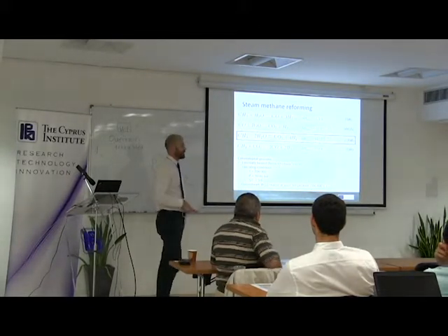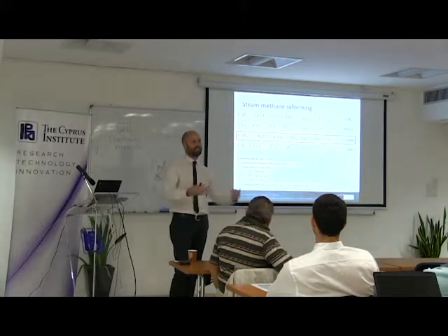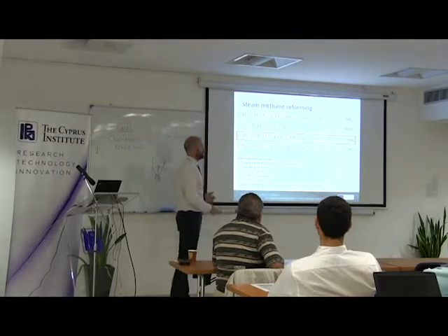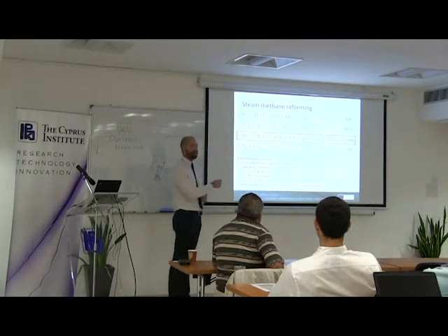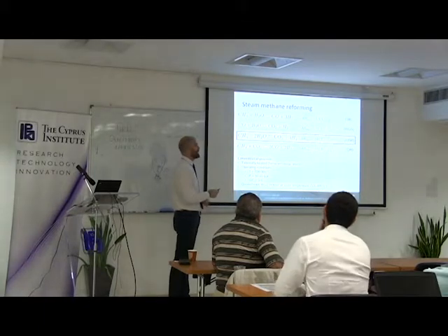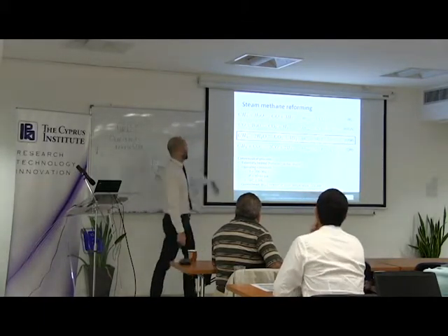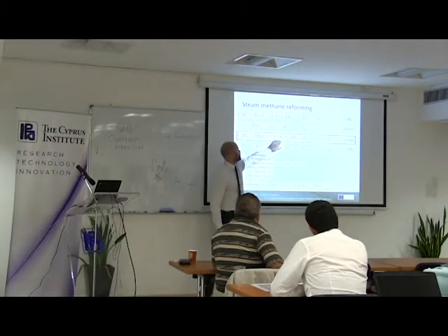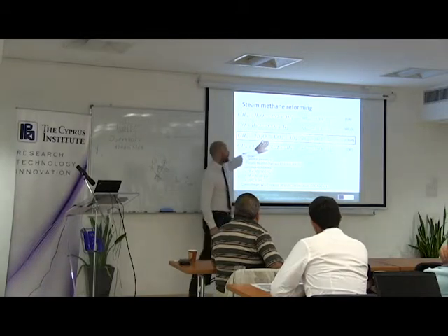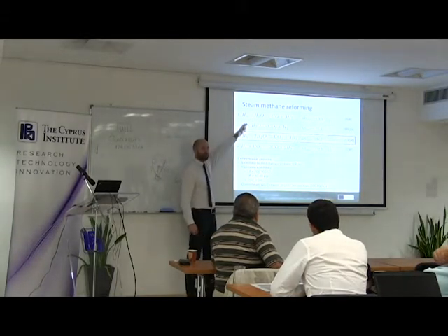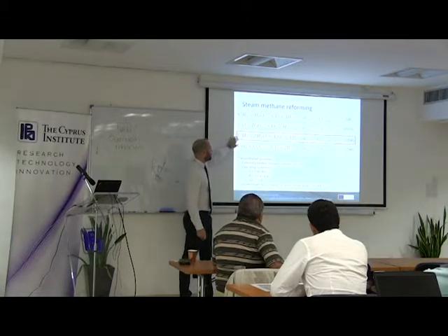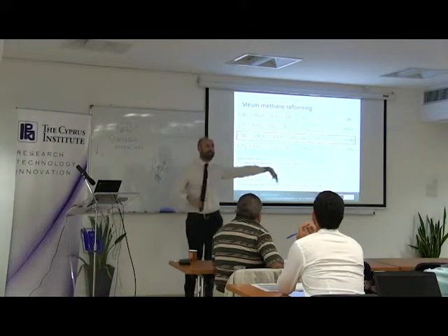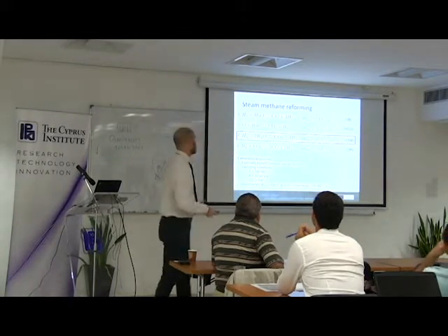Okay, let's start with the process which is closer to what we do today. So how do we produce hydrogen today? Mainly by this reaction here, steam methane reforming. We take methane, make it react with water vapor, and we produce hydrogen and CO2. This is the result of several other reactions occurring in parallel. The point is that the process is strongly endothermic, takes a lot of energy, and occurs at a very high temperature.